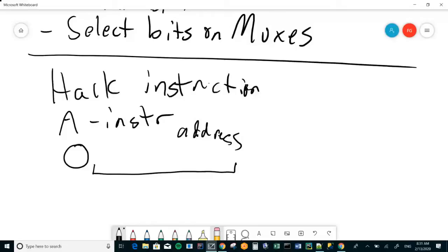It just makes the mental mapping between this instruction and what it's actually doing easier than if, say, we decided that the key thing was bit 7. I mean, we can do other crazy stuff too. Like we could say, well, it's like a binary number, but it's shuffled. So, the highest order bit is here, and then the next higher order bit is over here. And then the next one is over here, and then here, and then here. Like, we could do that as CPU designers, as instruction set designers. We could decide that that's what an A instruction is. But we don't, because it's crazy, right?